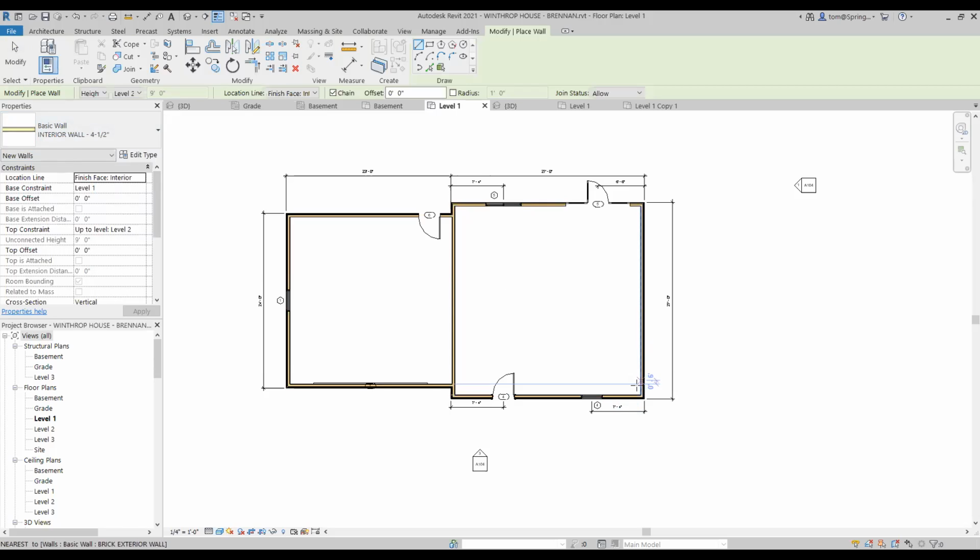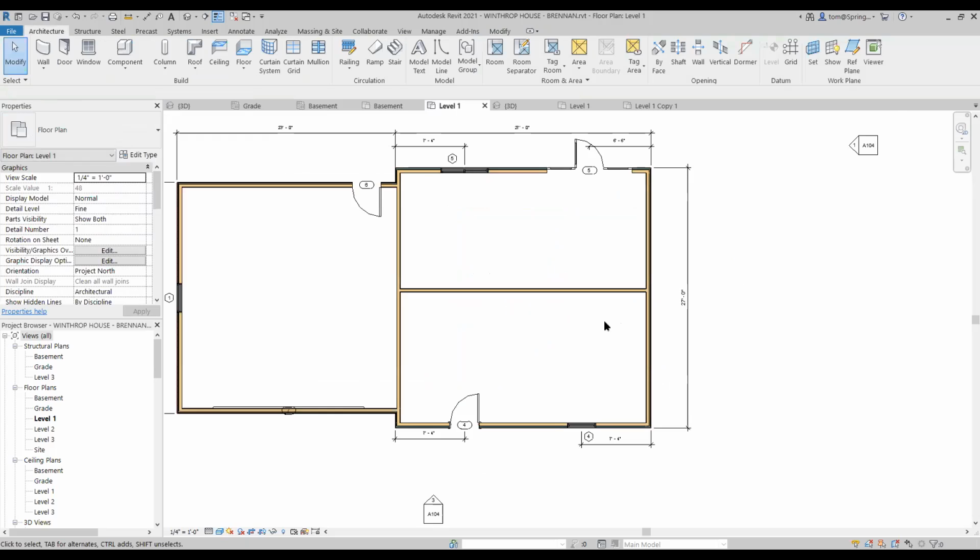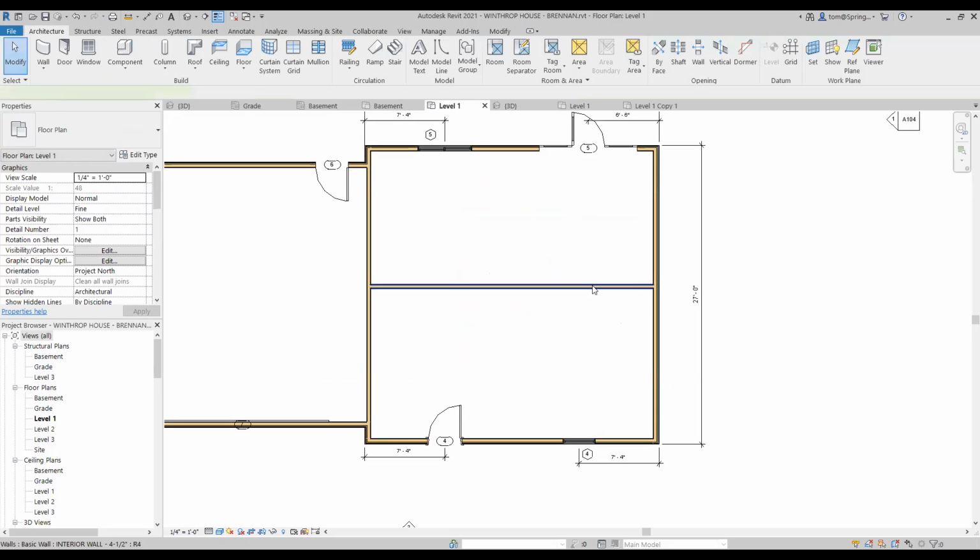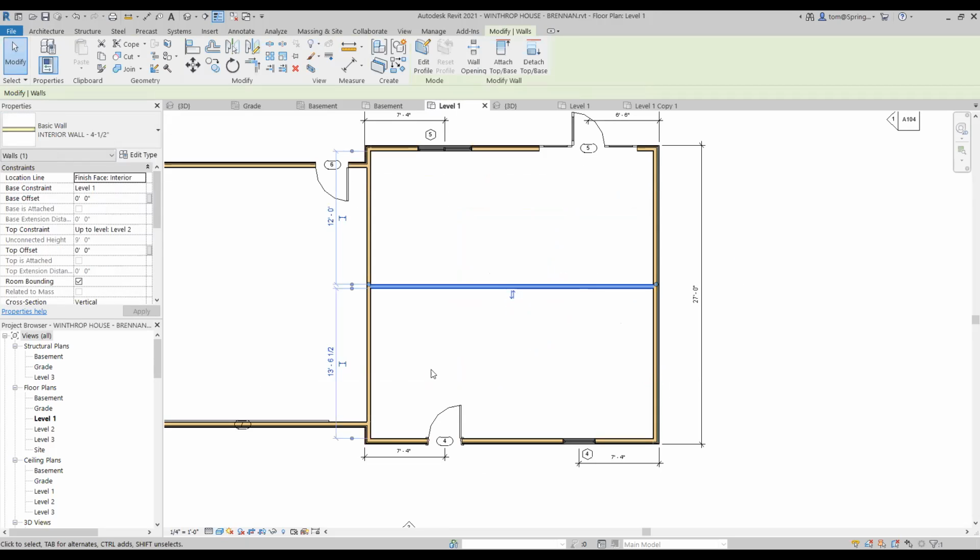And as I do that, it's going to give me a listing as far as where it's going to go. Now, right now, I'm just going to kind of pick. It's not finding where I want to go, so I'm just going to pick here and drag it straight across, and I'll fix it later. That is the huge advantage of using Revit. So when I go ahead and click on this, let's find out what that distance is. So the distance here is actually 13'6½", and it actually needs to be 12'9". So I'm close, but no cigar. So go here and make it 12'9".